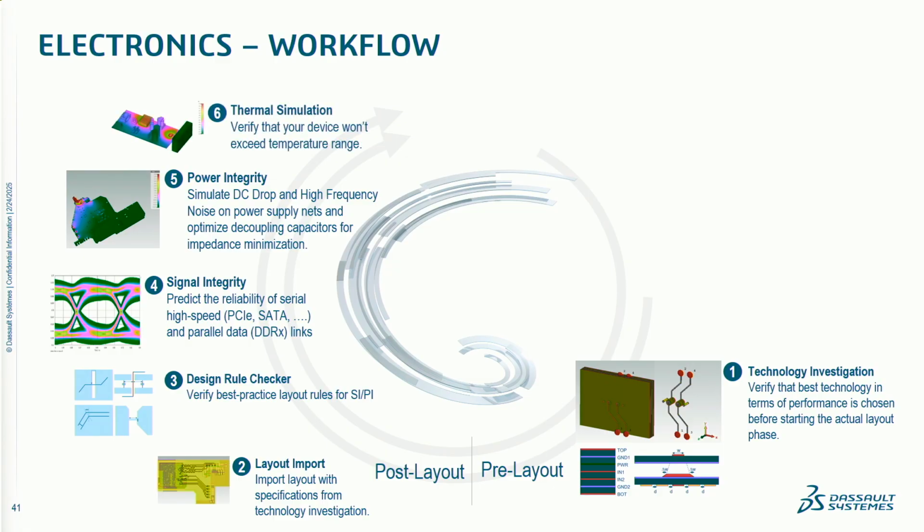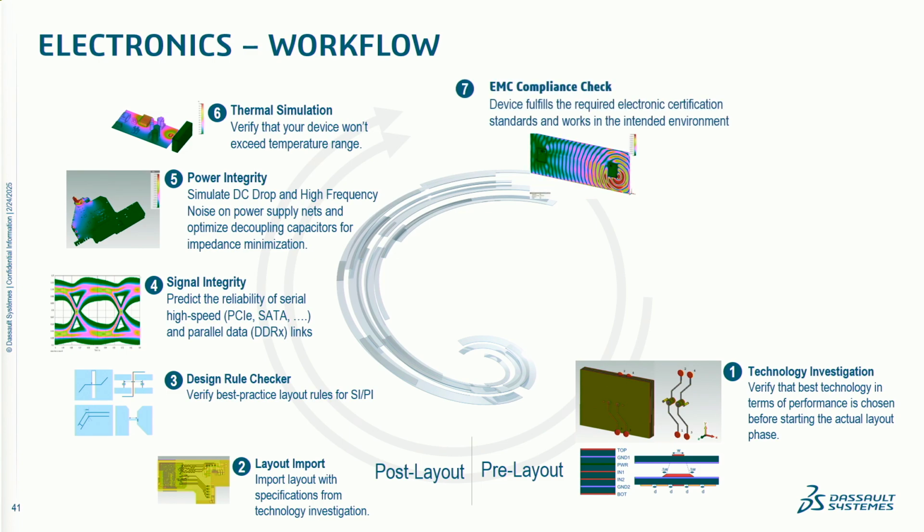Well, then we can actually look at thermal simulation. If you run a power integrity study and you find out the thermal losses in the components as well as the traces in the board, we can take those losses and directly transfer them into a thermal simulation as heat sources, right within the same software. All of this is without ever leaving the same window, guys. And finally, moving into what we call EMC compliance checking. This is looking at the radiated emissions and basically looking at a virtual EMC EMI test lab.